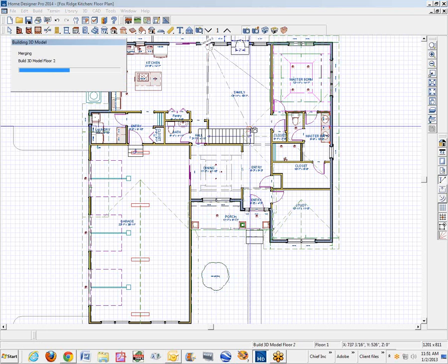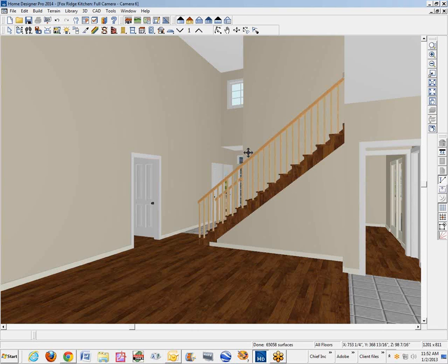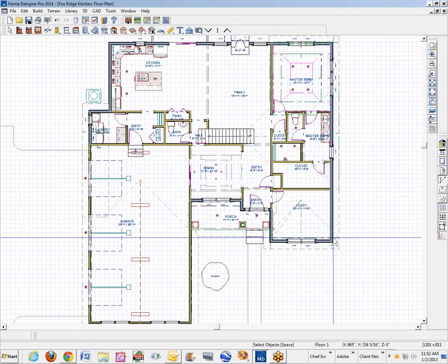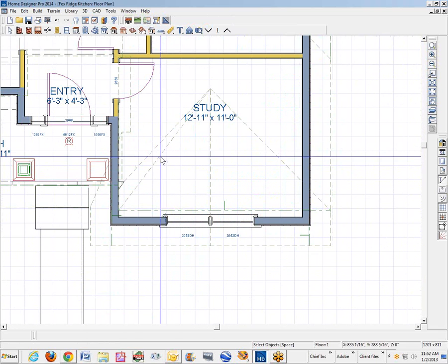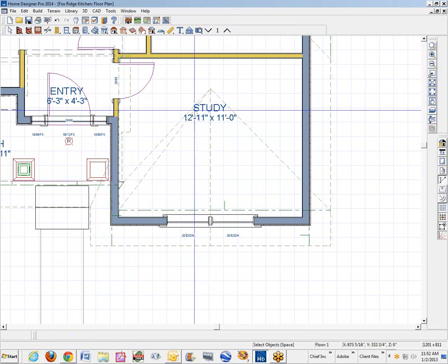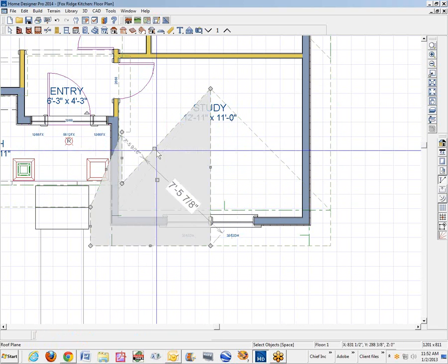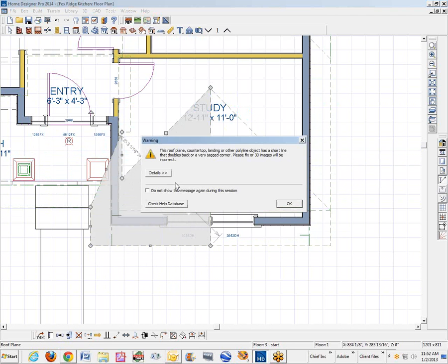But as you become more expert in the use of this software, then you'll stop doing things that add up to goofy solutions or unusual solutions. That's the only thing I found that worked that brought things to where they needed to go. Other things about the roof, see there's a bad connection here. We got this line on this roof plane not matching. We use the join roofs tool and join those two lines. That should clean that up.